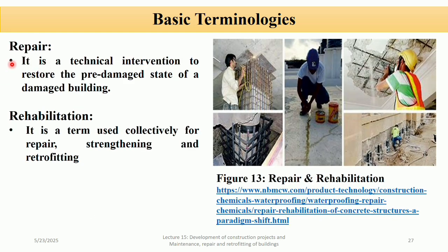Repair. So it is a technical intervention to restore the pre-damage state of a damaged building. We do repair to restore function and appearance and fix specific defects. For example, filling cracks, replacing broken tiles, or replastering a damaged wall.